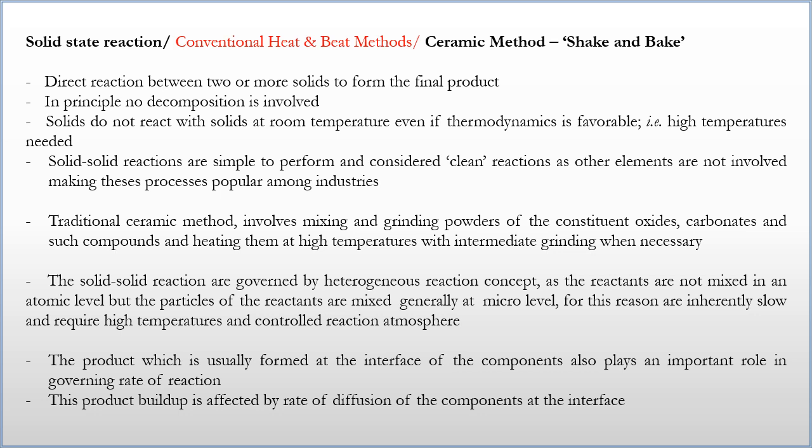The solid state reactions are governed by the heterogeneous reaction concept, because the homogeneous type of mixing which is seen in traditional liquid state reaction is absent here. The reactants are not mixed at an atomic level, but the particles of the reactants are mixed generally at micro level, and therefore these reactions are inherently slow because the mixing is not at atomic levels.